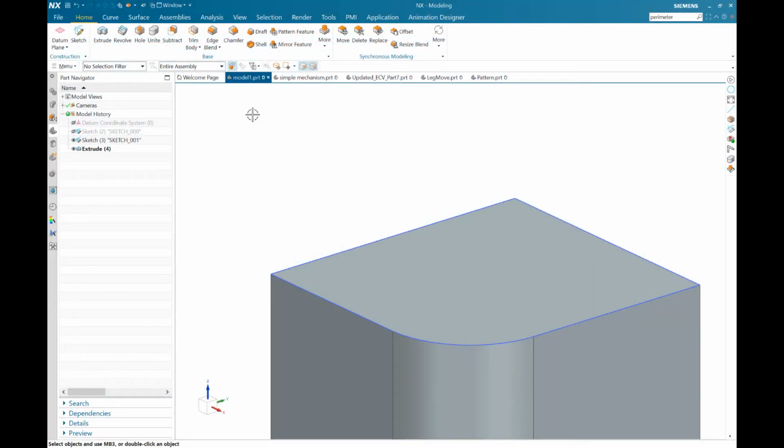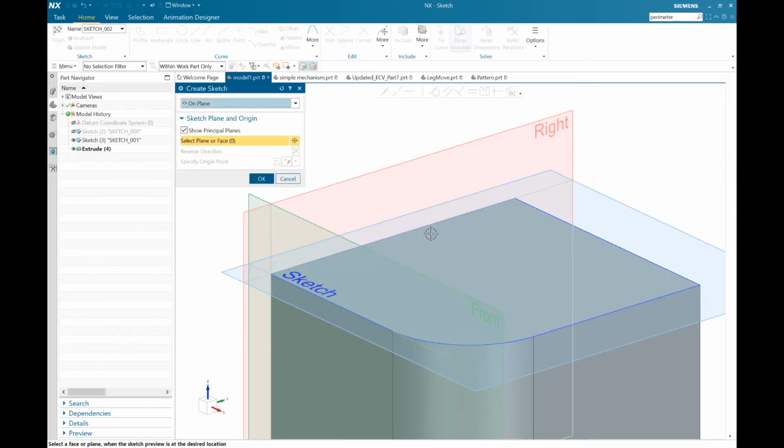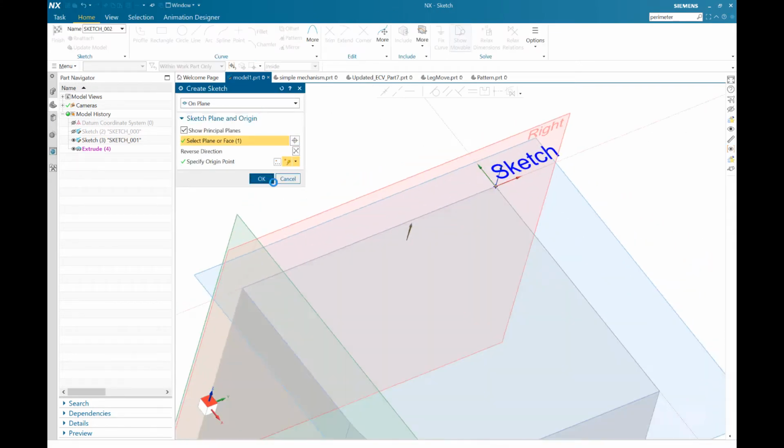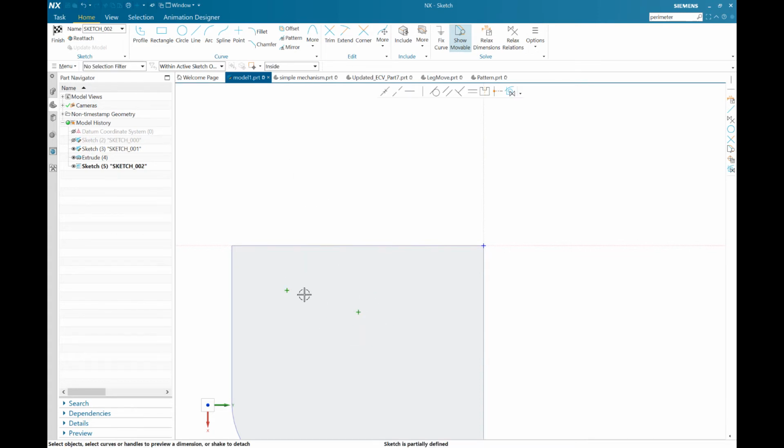So the question was, will that auto align, will that work within the hole command? Unfortunately, the answer is no, it won't. So if I create a sketch for my holes, I'm within that hole command, I place my first point, and you'll notice it doesn't give me the ability to touch off and align. So what I have to do is put in my second point and just align those with the horizontal or the vertical tool. Good question.